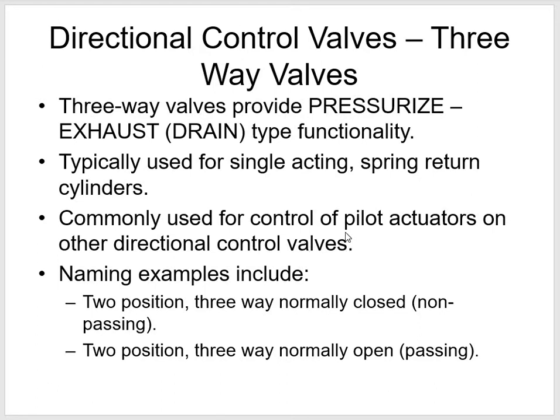Okay, so a three-way valve provides pressure and exhaust. Remember, our two-way did not allow us to drain or exhaust anything. Typically used for single-acting and spring return cylinders, commonly used for control of pilot actuators on other directional control valves. In other words, this is used in conjunction with another valve in the circuit.